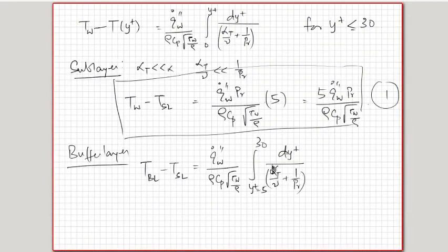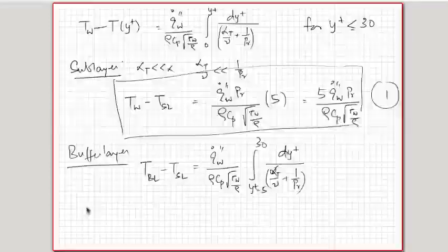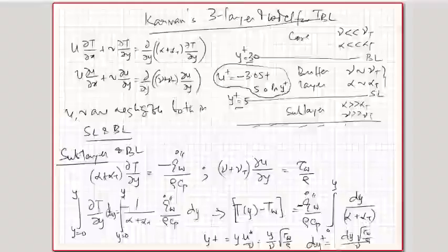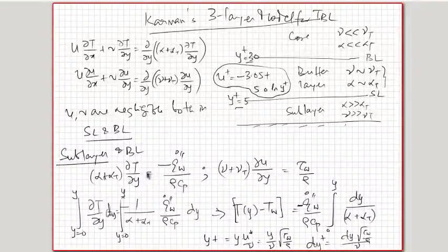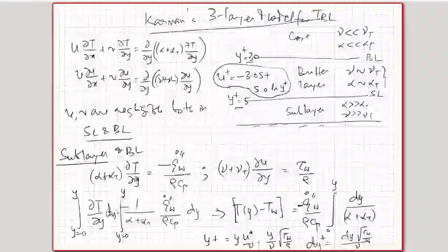Okay, now this alpha t by nu I would like to get from the results that I know in fluid mechanics, from the velocity profile expression that I have. So if I go from the momentum equation in the same way as I went for the energy equation, in the energy equation I wrote the q is approximately equal to q wall by rho cp in the entire region.